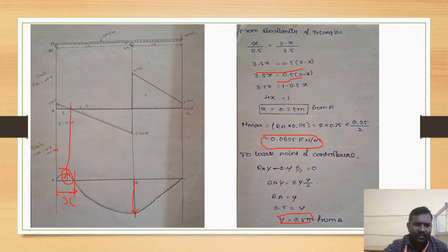That is the location where the shear force is 0, so finally the maximum bending moment is found there. We have already seen this in the simply supported beam, and the same procedure is followed here. So refer to our simply supported beam problem which has been uploaded in classes. I hope you all understand this overhanging beam problem. We have already discussed it in the classes very frequently, and we have discussed the assignment you have done. If you have any doubts, kindly ask me. We can clear it. Thank you so much.